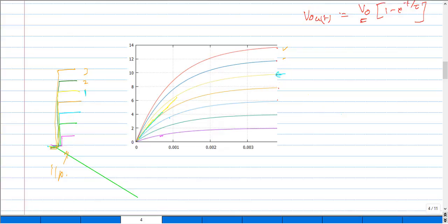This waveform is totally different, but the rate at which this is rising is totally different from the rate at which it is following. Okay, and then later on, after a while, if the output tries to follow, then the circuit has switched, has come back from the slewing back to the normal action, correct? And again, if I go for this, which is denoted with the green color, which is number 2, now what happens is the output doesn't follow this particular waveform, and it follows something like a kind of ramp output, okay? And after a while, it just comes back to this particular output, okay?